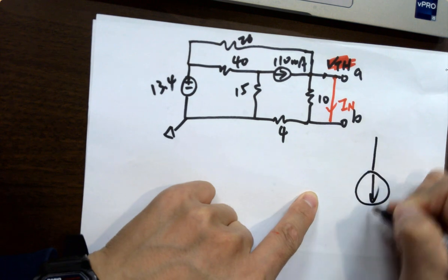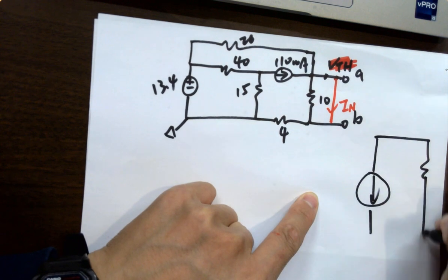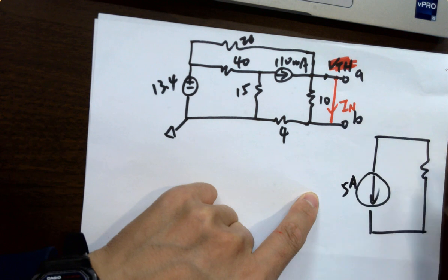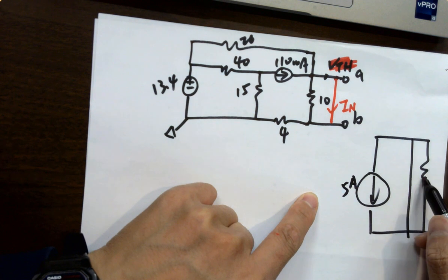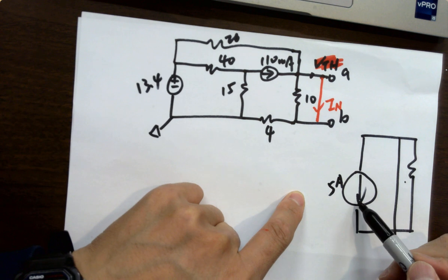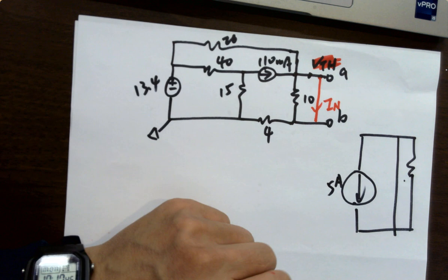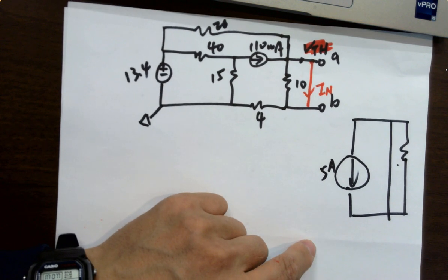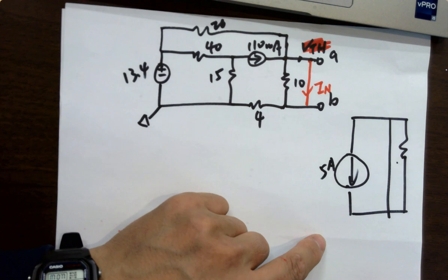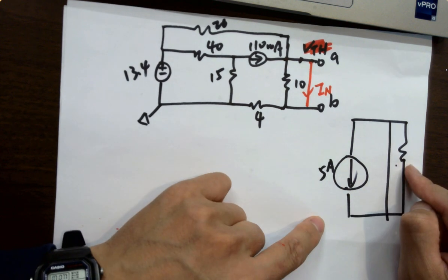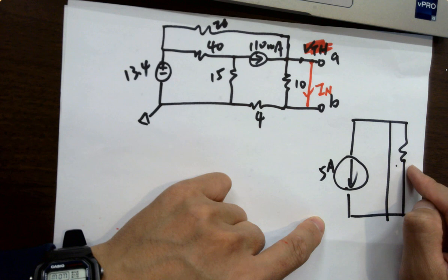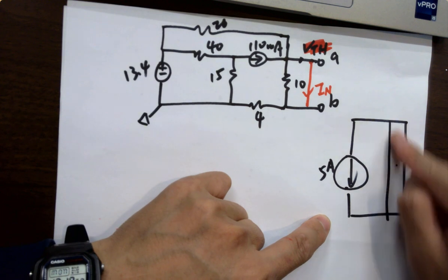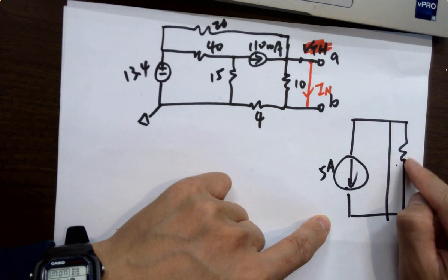Okay, another thing. If I'm drawing a current source, 5 amps, and I draw a wire here, is this getting shorted? Why? What does that mean, getting shorted? Physically, yeah, the voltage is the same. What else? The current is not going to flow through this guy if it's getting shorted. That's by definition getting shorted, because the current is taking a shortcut instead of going through another component.